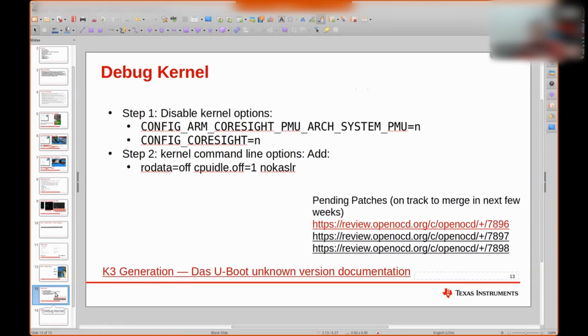The good is that you can iterate really fast. The bad part is every time you want to see the next level of debug, you have to add yet another printf and iterate again. If you're using a JTAG solution or KGDB, you can debug using the GDB interface. You have two options available: one is KGDB, the other is using a JTAG debugger.